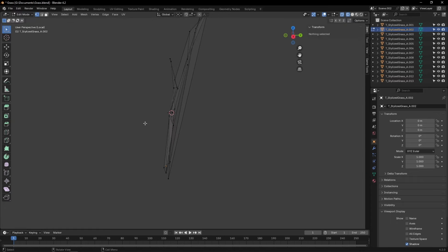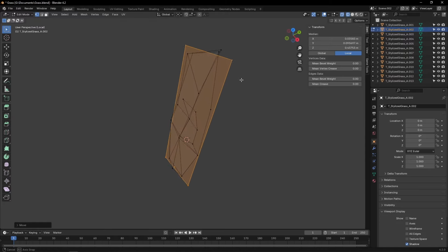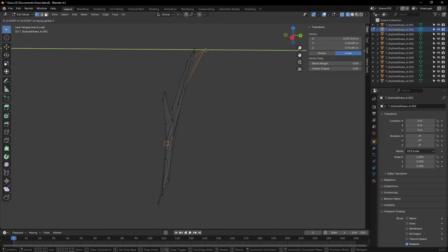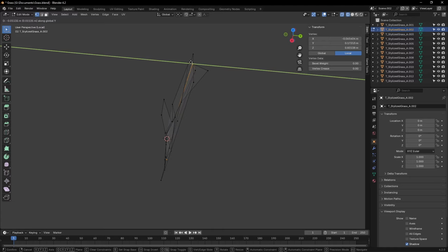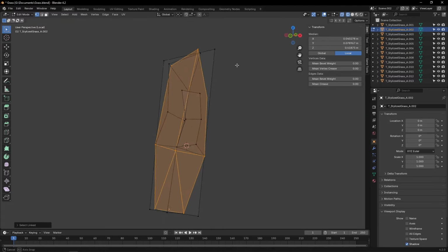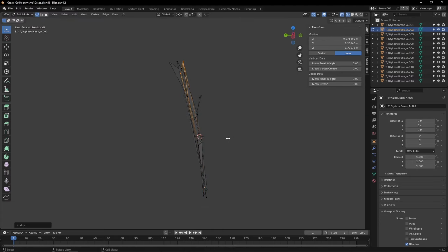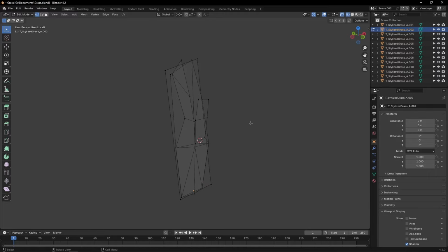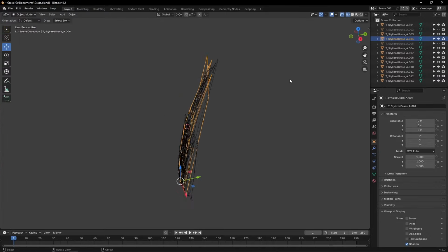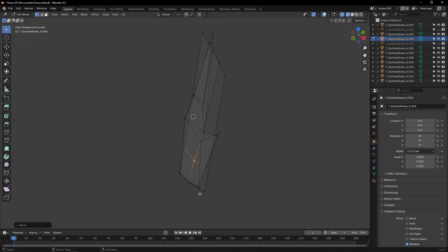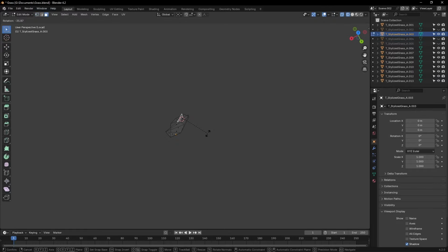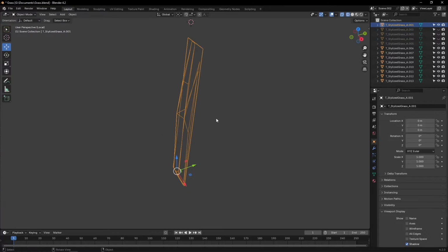So yeah, it's all about using your best judgment and trying not to deviate too much from the higher LODs, because you likely have quite a bit of geometry to work with for the LOD 0, right? So you can likely create an interesting volume, sure. But keep in mind that this LOD 0 is going to quite abruptly transition to the LOD 1 at some point, and then LOD 2 and so on. So there's a balance to find, right? Tweak too much the LOD 0, and the LOD switch is potentially going to be quite noticeable in-game. On the other hand, it's a good idea to leverage the higher vertex count and add some extra oomph to that flat card, if that makes sense.